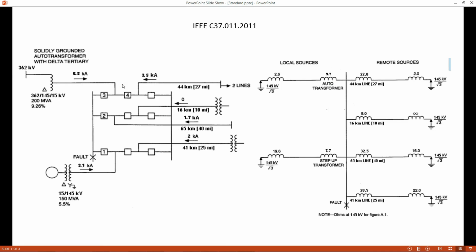So you know, it's always difficult to know the scope of the study, where we should stop modeling. So the advice for that is, you have to model the substation and the line going out of it until the next discontinuity. For example, here a transformer, or then here we separate in two lines. So you have to represent those lines going out of the substation. If it's connected directly to a transformer, then because of the big impedance of the transformer, it's enough. So that's, you know, something that comes with experience, but that's some advice we can give.